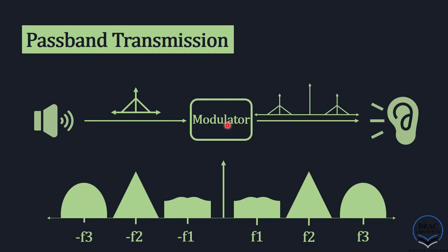Now, this is the magic. Remember the previous spectrum where three people were talking simultaneously. In that case, there were similar shapes like this, and all the spectrums were stacked in the low frequency range, right? All of them were stacked in the same place. But now, as the modulation process is taking place, those spectrums are shifted to higher frequencies and shifted to different frequencies, most importantly. Even though they're still overlapping in time domain, these three signals are well differentiated in frequency domain.